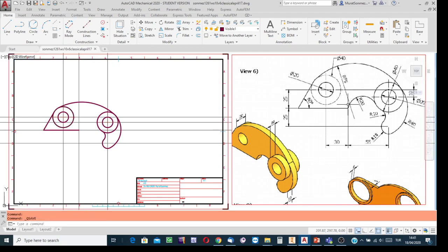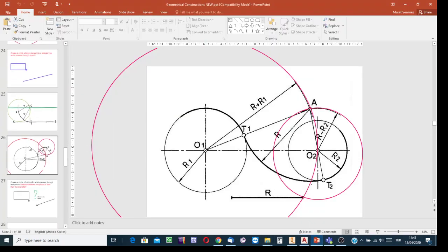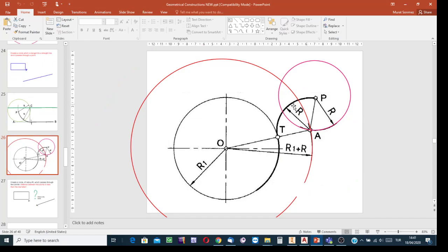And then now for this arc, this is the solution. About point P, create a construction circle. About the center of the available one, create the other construction circle. The size of the one about point P is equal to the size of the demanded one.